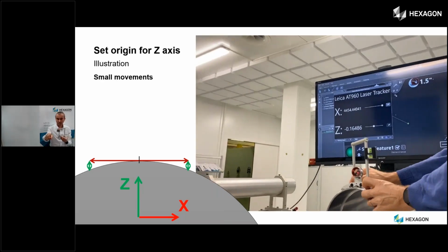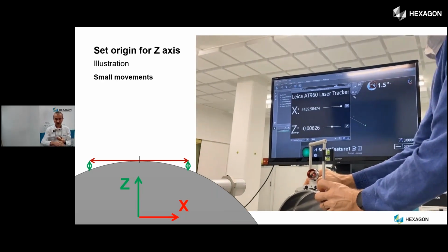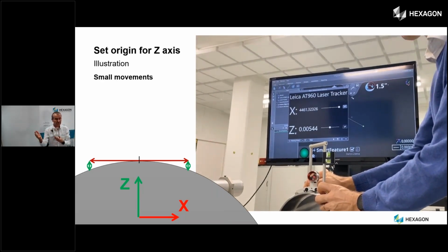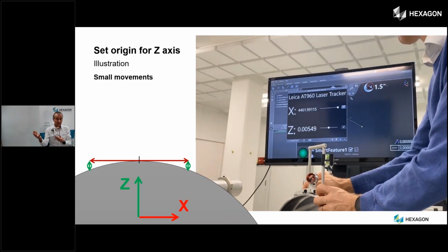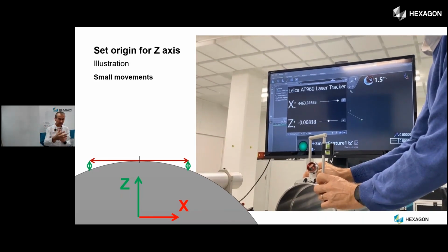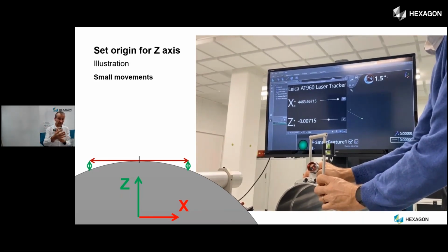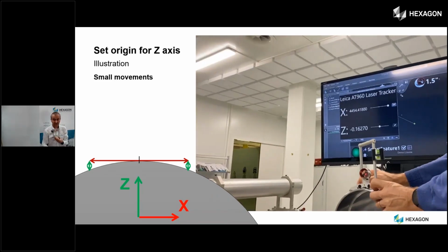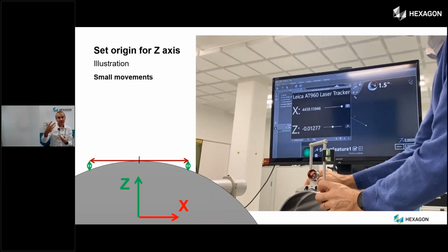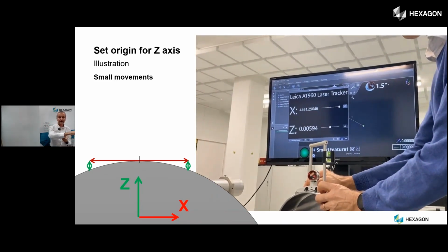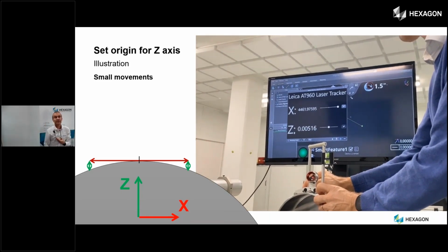Now you may just have a look at the values, 54, going up to the right side, going to 62. And now we may have looked what was the set value at the beginning, 0.1 millimeter, in the end 7 microns. So it moves around 100 microns while X is moving by 8 millimeter.